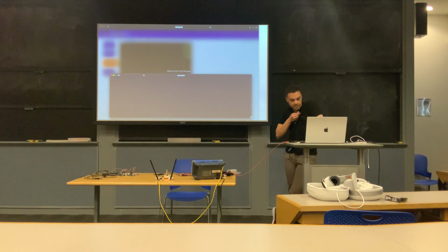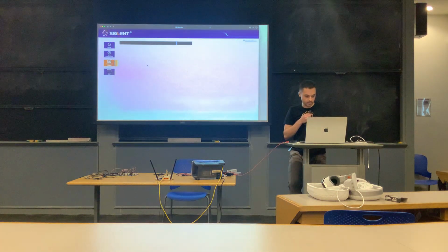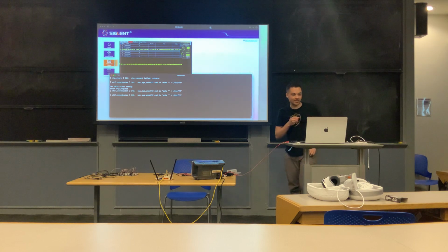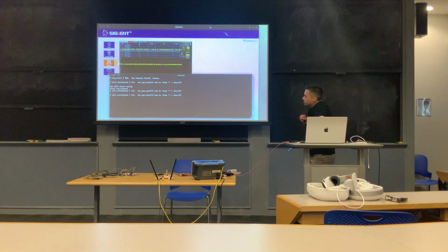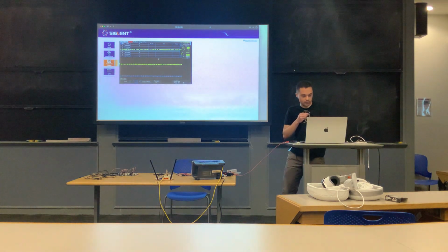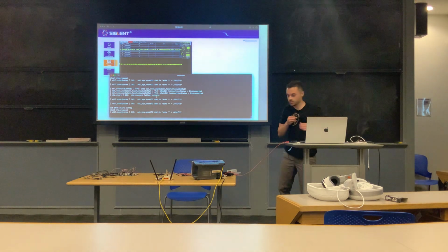And so I'm now connected into the serial port. Let's just wait a second to see if that data comes back. And I'll bring the scope here too. What is adding to casting? I'll talk about that in a minute. So you can see we have that data. We have this NTP connect failed return stuff that we saw before. So we're able to read the data that was being sent on those lines. You can see we actually have a live view of the data being sent on the oscilloscope, and we can also see what's going on here.